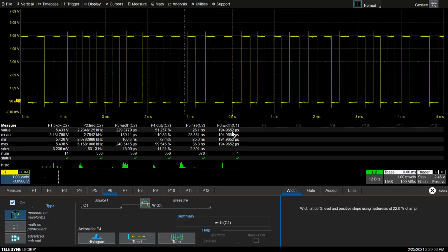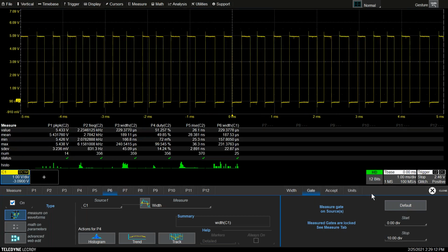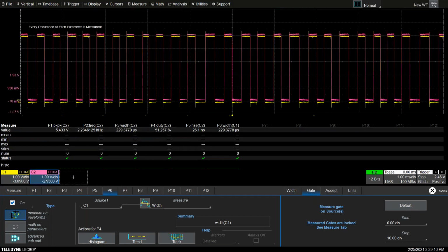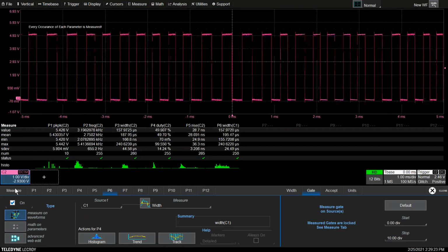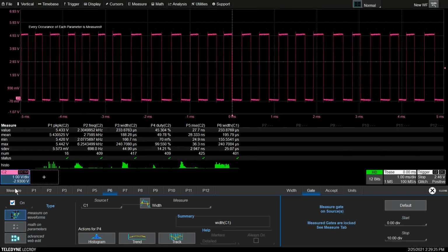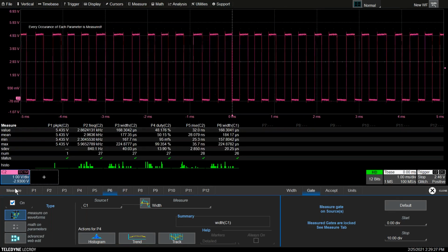You can define all the same location as well within the waveform acquisition if you vary the gates. I'm going to just go to gates here and say, there we go. Let me reset this, and I'm going to turn on channel 2 again, shut off channel 1, and make my next point. Okay. Clear sweep, single shot. Within this waveform, you may be acquiring it as a single shot. And so that's what we did here.